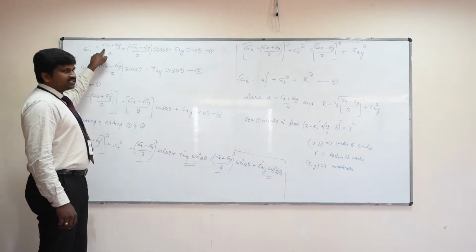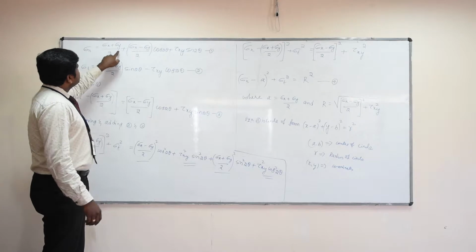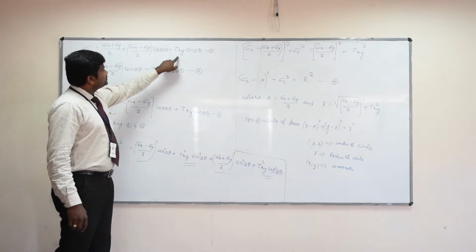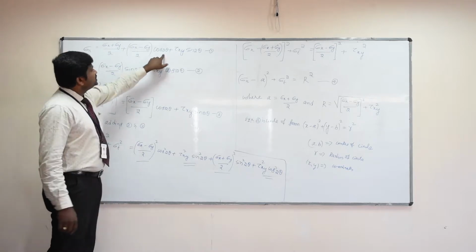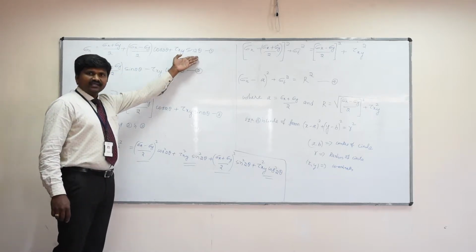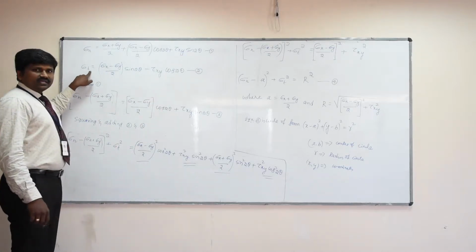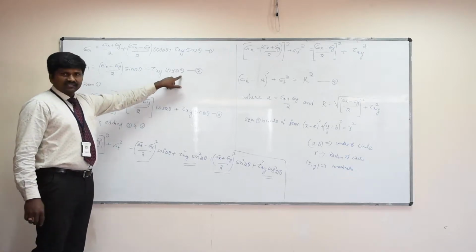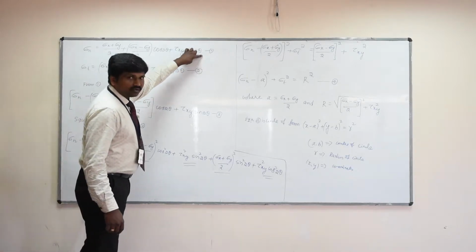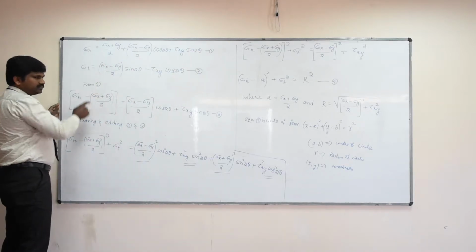So here sigma x is the stress acting in the x direction on a two-dimensional element, sigma y is the stress in the y direction, and tau xy is the shear stress acting on the same element. And theta is the inclination of the plane on which we are finding the stresses. Similarly, equation 2, sigma t, gives the shear stress acting on the plane which is inclined at the same angle theta. So we take equation 1 and equation 2 and we simplify equation 1.